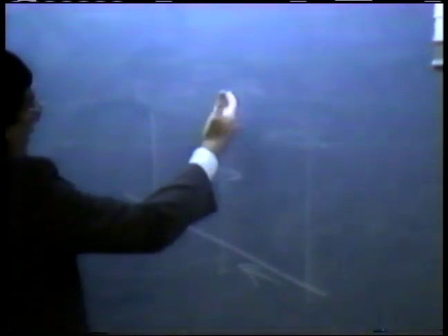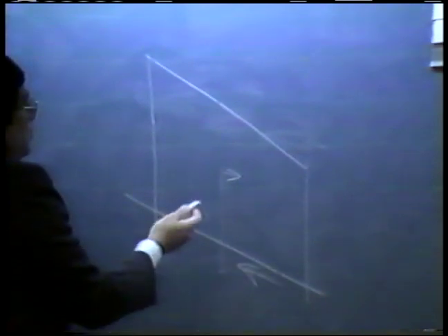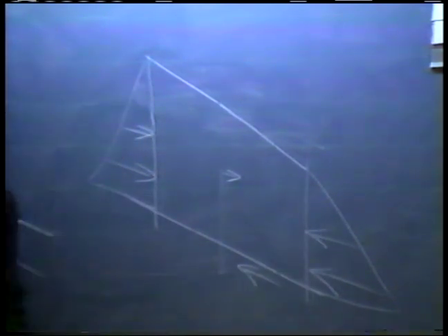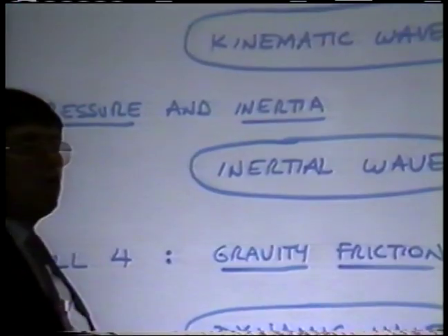For the general condition, you're not going to have the water surface slope and bottom slope parallel, so you're going to have a situation like this, exaggerating this, and you're going to have a pressure in here which is different than the pressure in there. We assume, of course, for gradually varied unsteady flow, that the pressure distribution is going to be hydrostatic. For most cases, we can get by with it. Since these pressures are different because the depths of flow are different, there's a pressure difference. A pressure difference leads to the pressure gradient, which leads to a force.